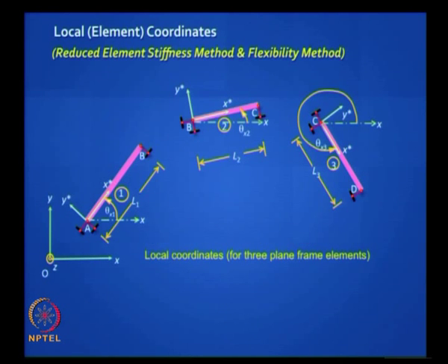So let's look at this problem. We did this earlier, right? Now I have given 3 supports, okay, I can give any 3 independent supports. You see these things? I have actually made it simply supported. These 2 rigid links say that this joint cannot move. This rigid link says it can move horizontally, it is like a roller support but it can't move vertically. Now this element is stable. If I apply loads on it, it will resist those loads.